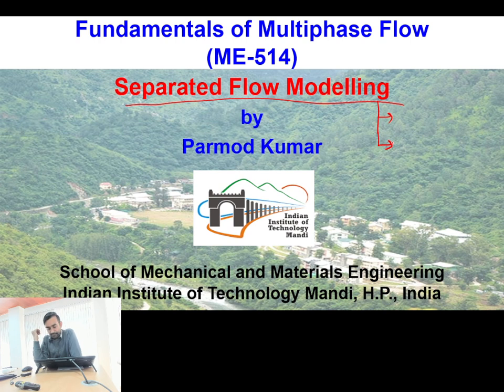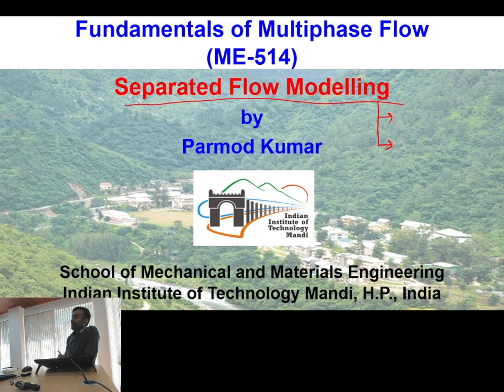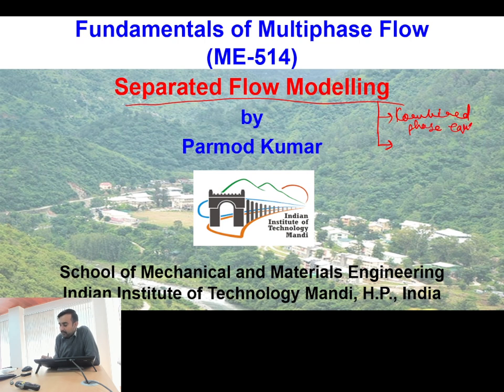Now, when the separated flow modeling approach evolved, in the very initial days, people simply used the combined phase equations, but they relaxed one condition of the homogeneous flow approach, and that condition was same velocity.